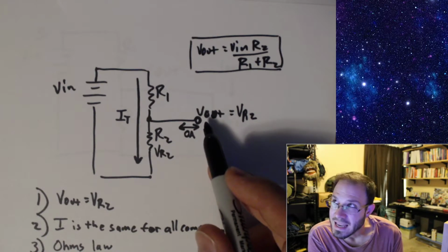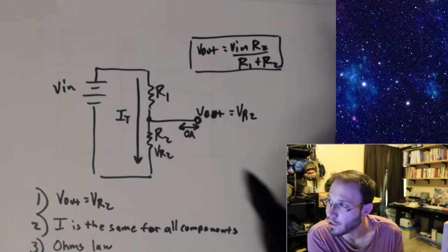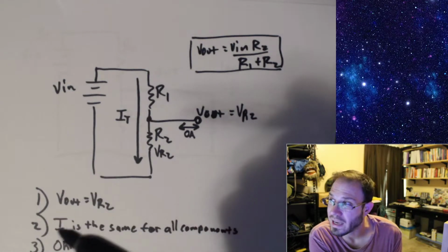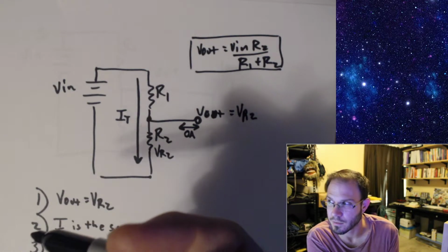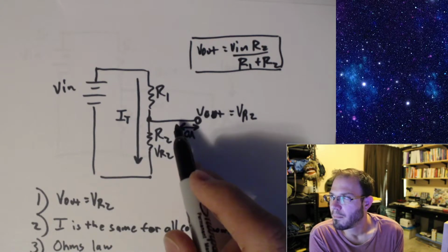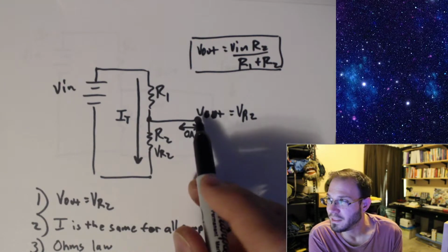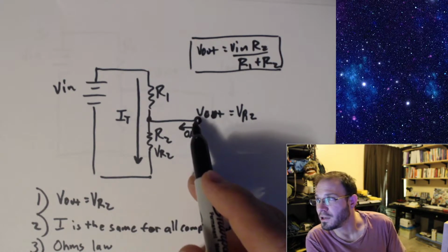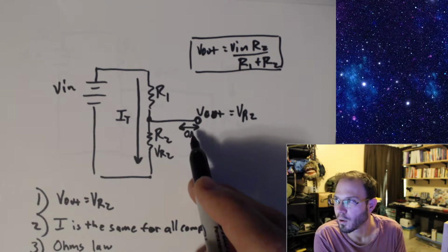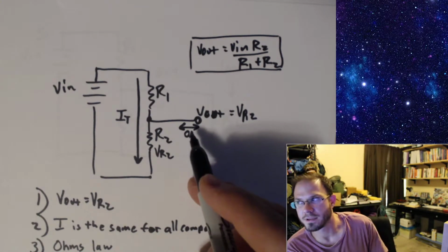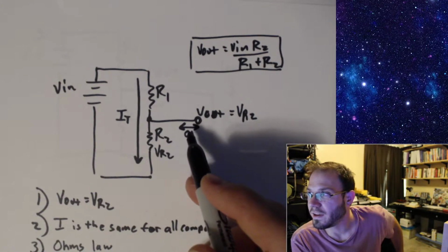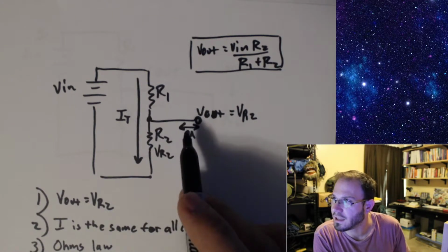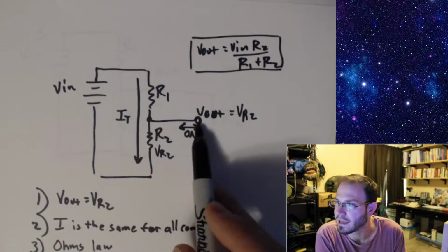Those pins on the actual integrated circuit, the computer chip, use very little to no current, or we can consider it at the very least to be negligible. And so there's plenty of times, actually more often than not, the things that we do attach to a voltage divider end up using little to no current, or if it does use current, it's in the microamps. So it's so small we don't even have to bother calculating it, which is kind of nice. But no, this point is not at all acting like a ground.